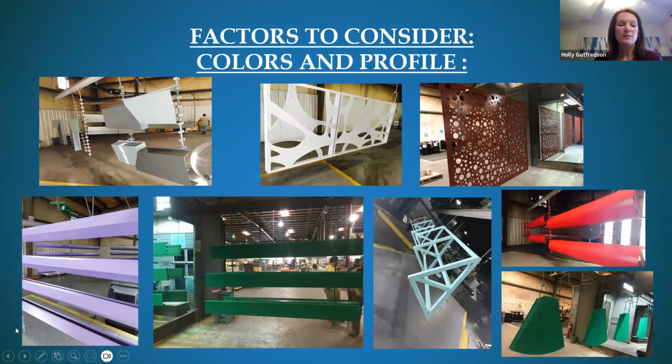So definitely, we talked about exotics. We talked about all the different types of paint that are out there. With PVDF, you can do micas, metallics, you can do two-tone. There are some wonderful color shift products available in extrusion coating. Just a variety, endless types of options. So that's exciting. But again, let's talk about the location of your project. If it's going to be in the middle of a super arid environment that gets tons and tons of sun, you may not want to go with an exotic red. You may want to choose a more muted color to make sure that quality lasts a lifetime.